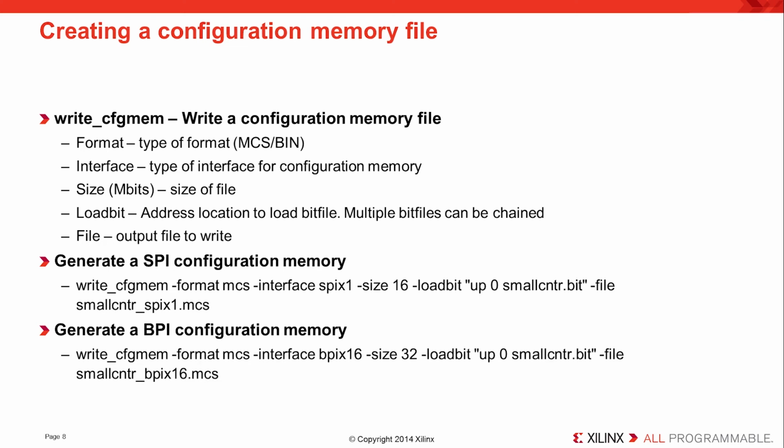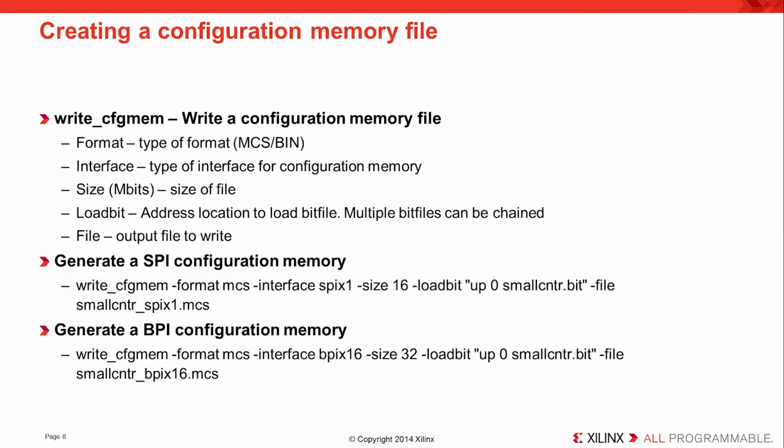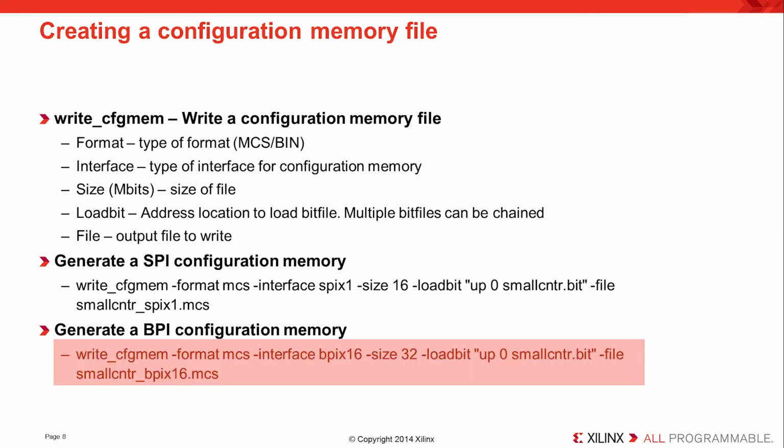For the SPI configuration memory, the command we would run is this. Note that the bit file must have the correct configuration mode selected to align with the interface here. For the BPI configuration memory, the command we would run is this.